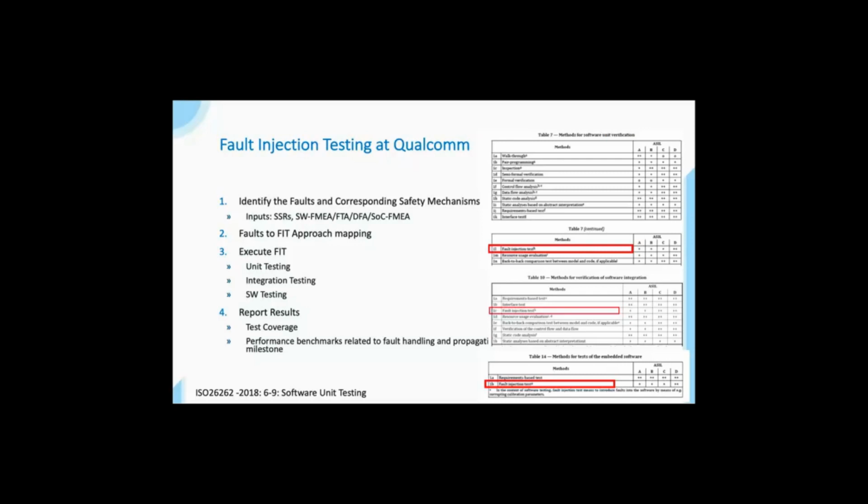There's nothing very special in safety except for one of the key differences, the fault injection testing. So we have to spend quite a bit of time with fault injection testing. Again, it's very complex for us because it's not like we have a single ECU into which you can generate faults easily. You have all these sub-processors and accelerators into which we have to generate faults.